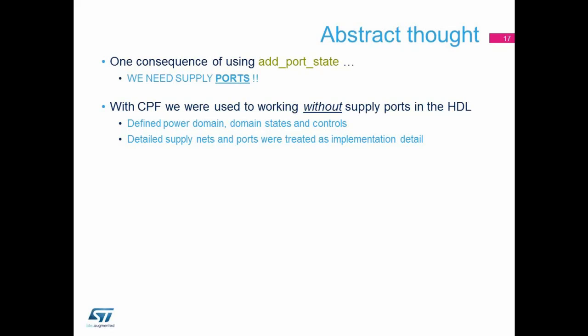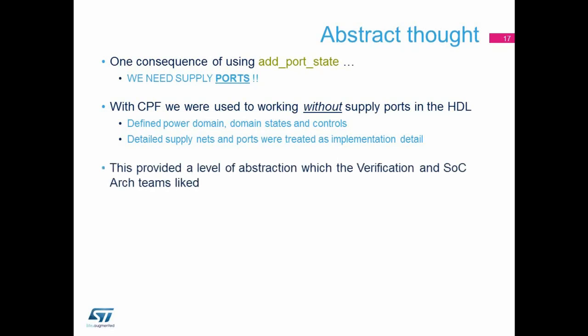We had power domains, we had domain states, we had controls, but the implementation details of supply nets and supply ports we were leaving till further on in our flow. And that sat pretty well with the verification of the SoC Arch teams, because they liked the idea of not having to get their hands dirty with implementation details and just concentrating on verifying and designing the function of the design.